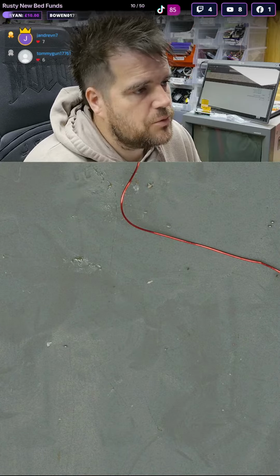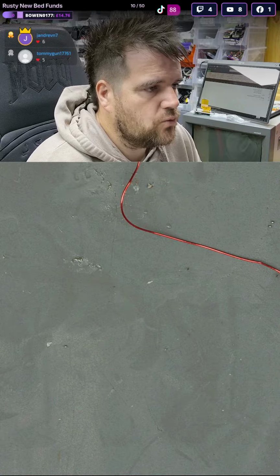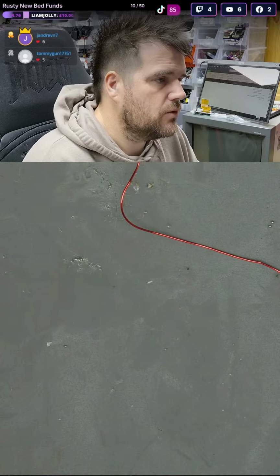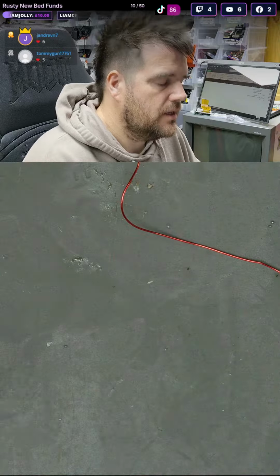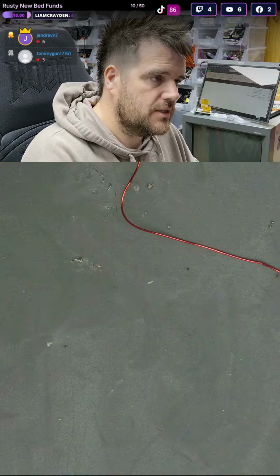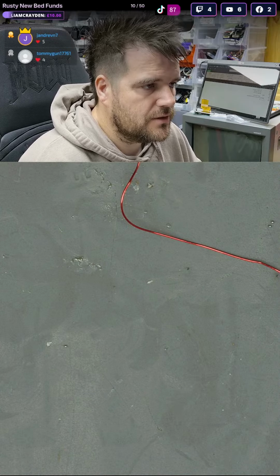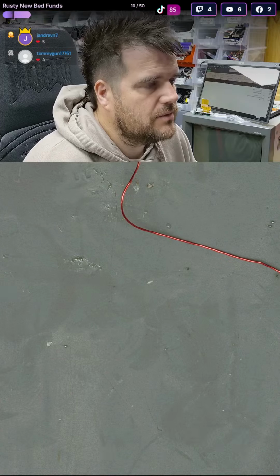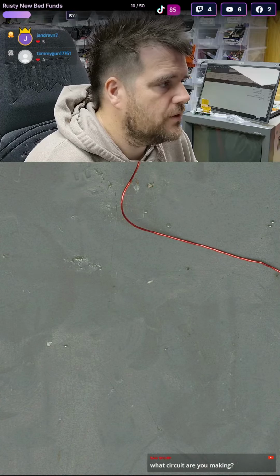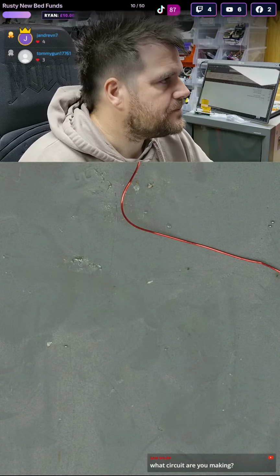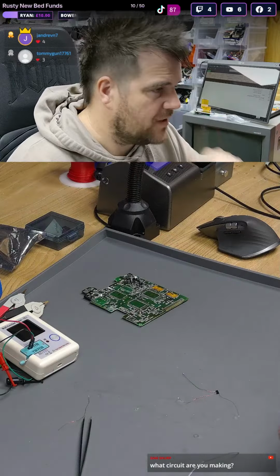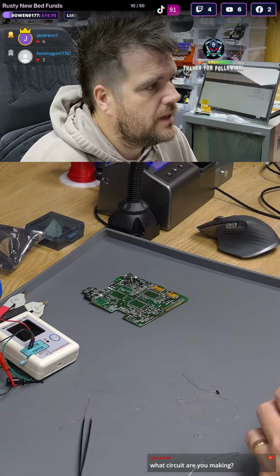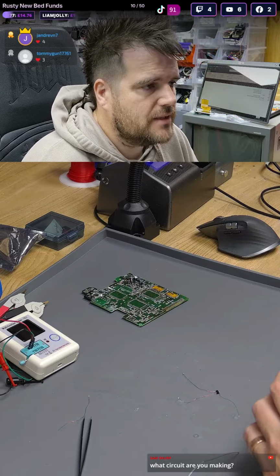Clean your cartridge port with white vinegar that's warm. Put vinegar in the microwave in a little bowl for a minute so it's pretty hot. Then you can either tip it in the cartridge slot slowly so it touches, but ideally you want enough vinegar that you can dip the cartridge connector in and leave it for no more than a minute, which is more than enough. Then inspect the cartridge port. You could always try to bend the pins up with tweezers, then try again, clean your game with IPA and see if you get game load.